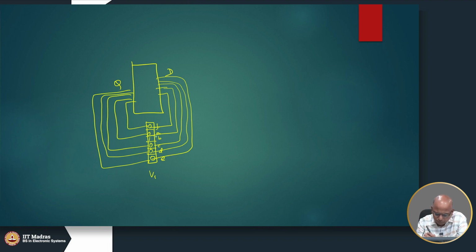Now, in order to apply V2, I can try to just shift this guy. So A will go from 0 to 1, B will go from 1 to 0, C will remain 0, D will remain 0, E may remain 0, F will become 0. This may result in the transition being launched, and then we do a capture.